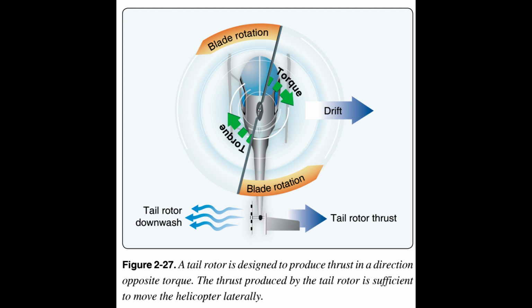By mounting the tail rotor on top of the vertical fin or pylon, the anti-torque is more in line with or closer to the horizontal plane of torque, resulting in less airframe, or body, lean from the tail rotor. Also, having the tail rotor higher off the ground reduces the risk of objects coming in contact with the blades, but at the cost of increased weight and complexity.